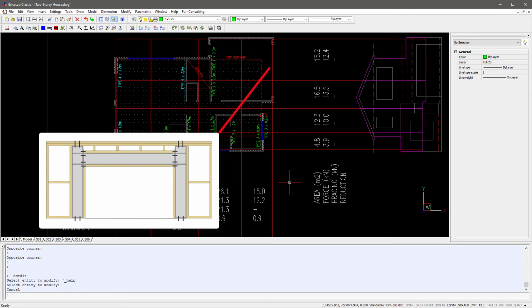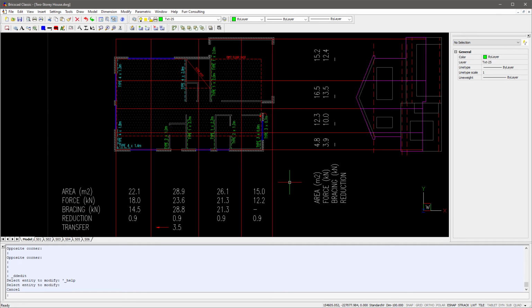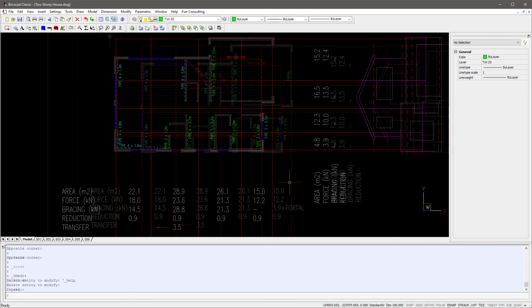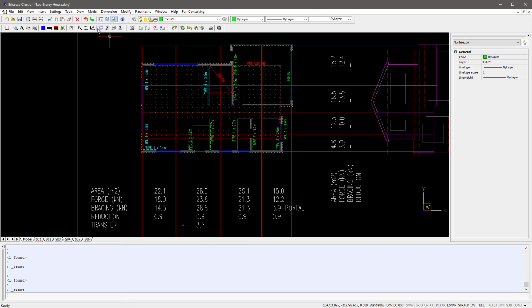Designing a brace frame has a bit more to it than just setting out some standard bracing, and its design will be integrated into the overall framing design of the house, so we'll be covering it in a later video. For now, we'll just designate it as taking 8.3 kilonewtons of force. At this point, it should be pretty clear how we will go about the rest of the bracing design, so we'll skip ahead and summarise what we'll do for the east to west direction.